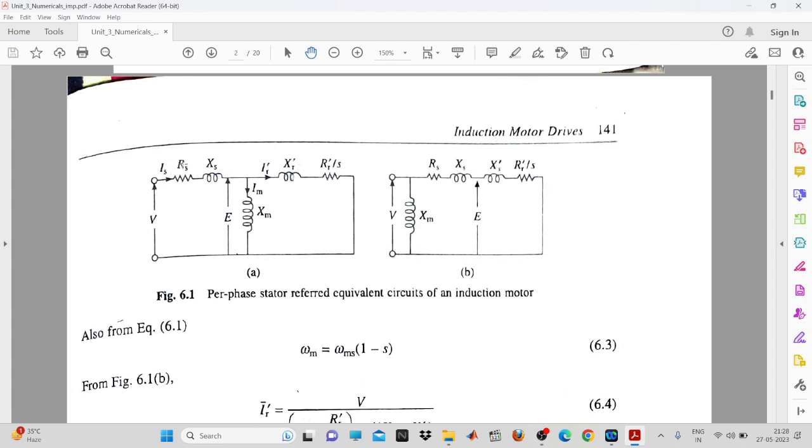And you can see that this RS will be the frequency independent component, whereas XS will be the frequency dependent component. Just take a note of it. Now there will be the reactant, that will be the magnetic reactance. So basically, we always ask people what is the function of the reactive power. The function of reactive power is to magnetize the air gap.